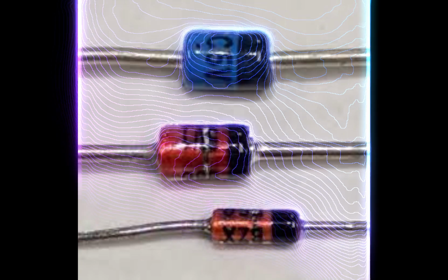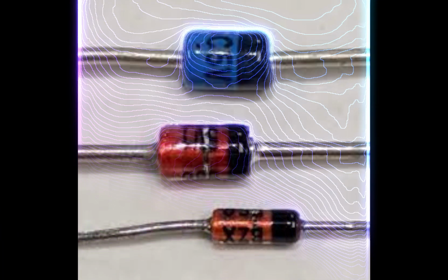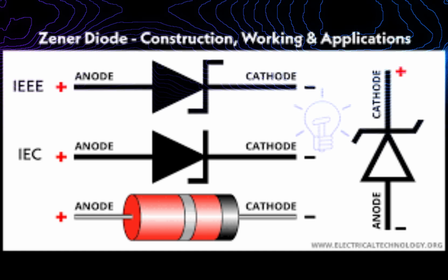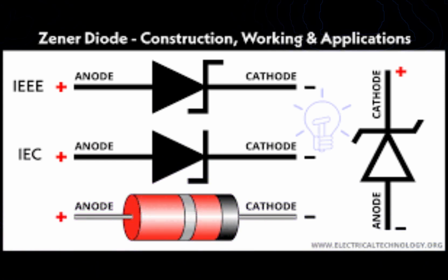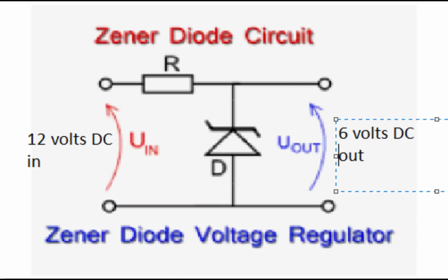Voltage shifter. When applied to a circuit with a resistor, Zener diodes act like a voltage shifter. The circuit lowers the output voltage by an amount equal to the diode's Zener voltage. Waveform clippers. This device reshapes a signal and prevents voltage spikes from affecting the circuits connected to a power supply.